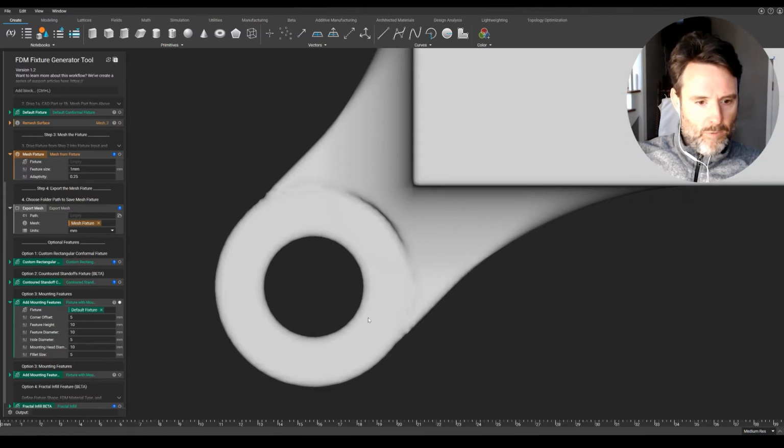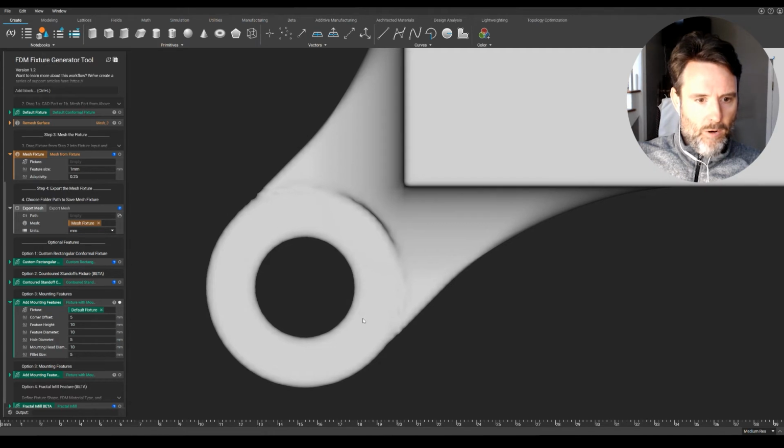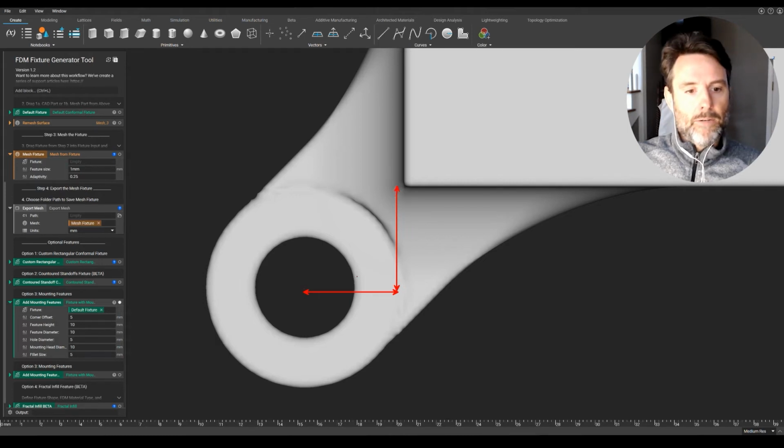So if I zoom in somewhere and put the center of my hole right around the 15 millimeter marker, and I go over 5 millimeters to about 20, that's what that number is, the corner offset. It also is the same value in the Y direction. So those are going to be the same. So you're just forming a clean triangle, equilateral, or a triangle with the same distance on the X and Y axes. All right, so that is the corner offset.